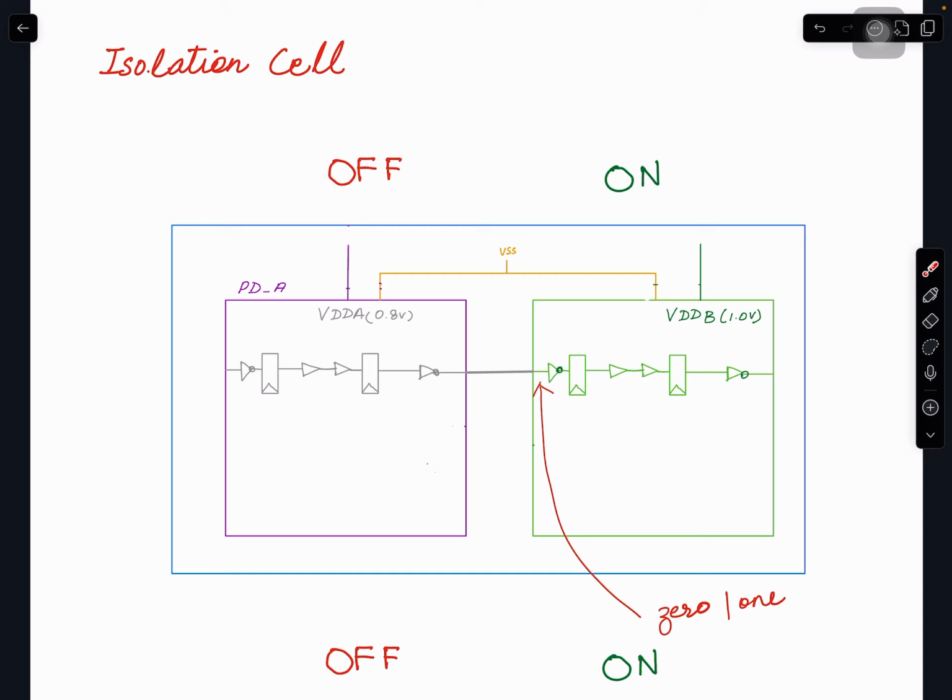Understand that? And even in our physical design, sorry, in our circuits, in our databases, a cell whose output is not connected, dangling, that is okay, right? It's not driving anything. But the input we cannot leave dangling. You have seen that tie off; we have to tie it off, tie high or tie low. You need to put 1 or 0 on it. If something is floating, you need to connect it to supply voltage or to ground. And for that, we use tie high cells and tie low cells, depending upon what voltage level you want to connect.